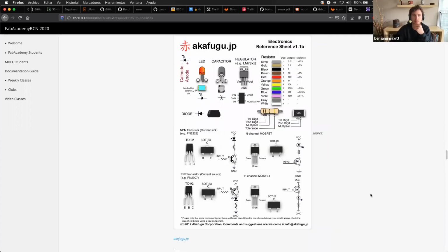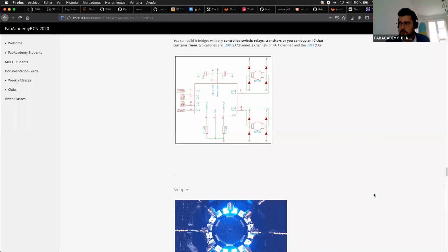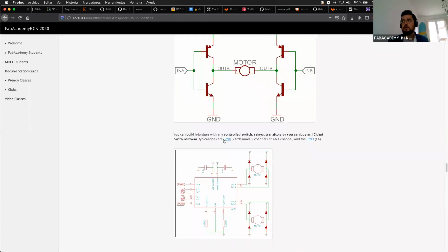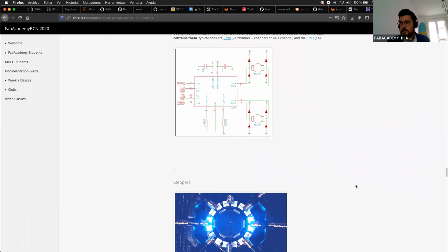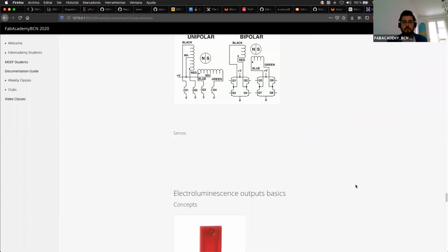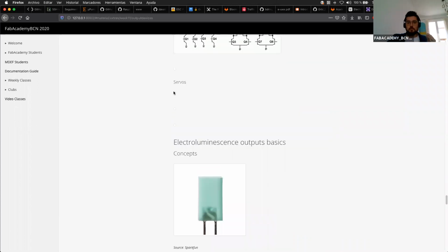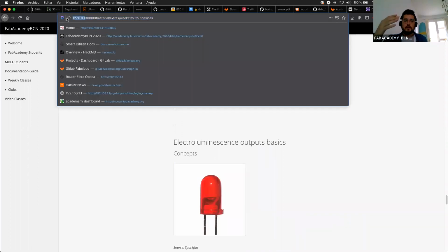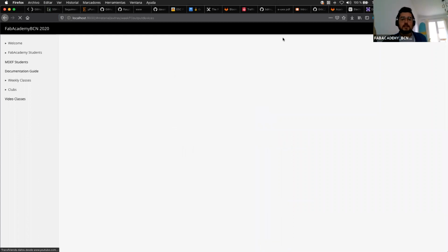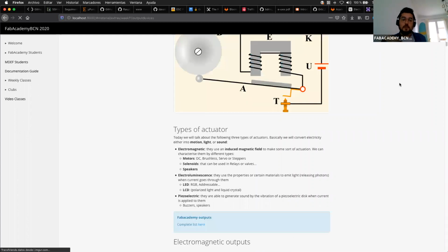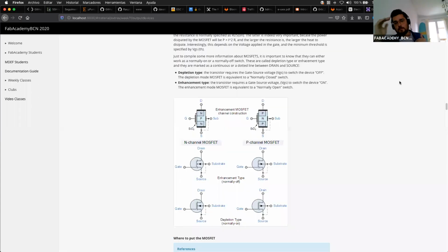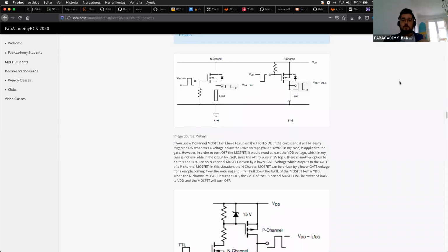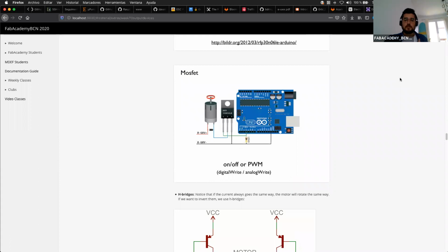Usually, just to have applications, how to choose where to use a P channel and an N channel. P channel, as you need to pull it low from the high state, if the current that you are driving at the voltage is really high, for example, let's say you are controlling a pump that is 24 volts and your Arduino is 5 volts, there is a big difference in voltage. As the Arduino needs to pull from 24 to 0, it will have a lot of trouble pulling that range of voltage low.